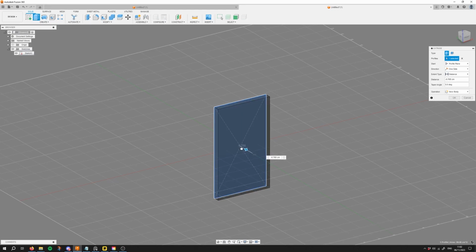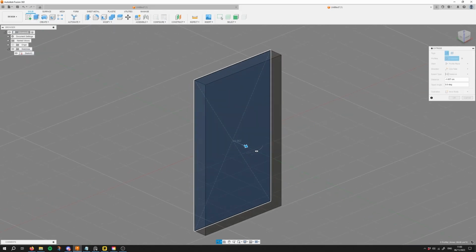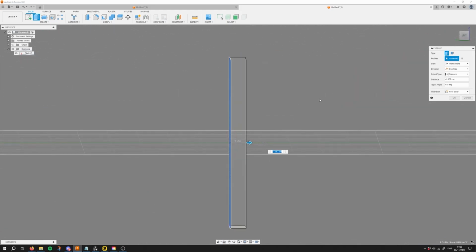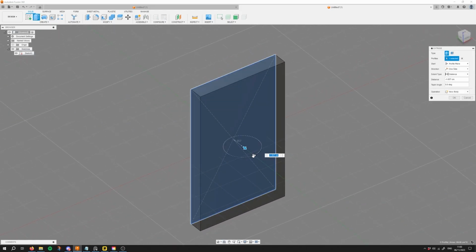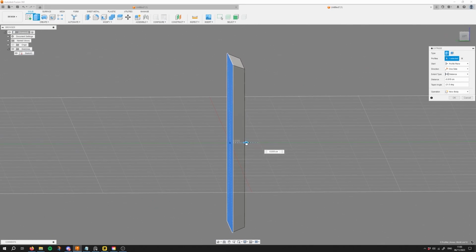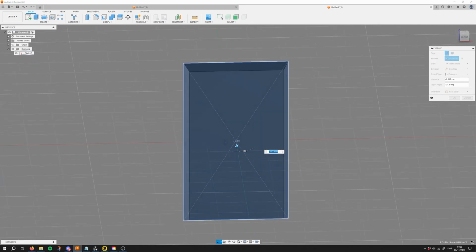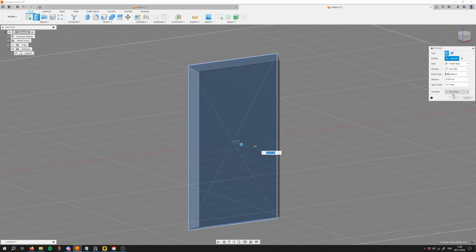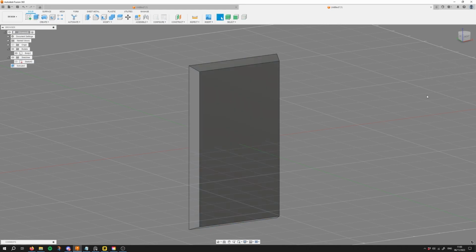We just have to simply drag it out, and this will create just a simple rectangle, but we want it chamfered. So we can just drag the slider over here and see what looks right. Maybe a little bit smaller. There we go. And just press OK to create a new body. You can select Cut, Join, Intersect, but we just want a new body, so we press OK.